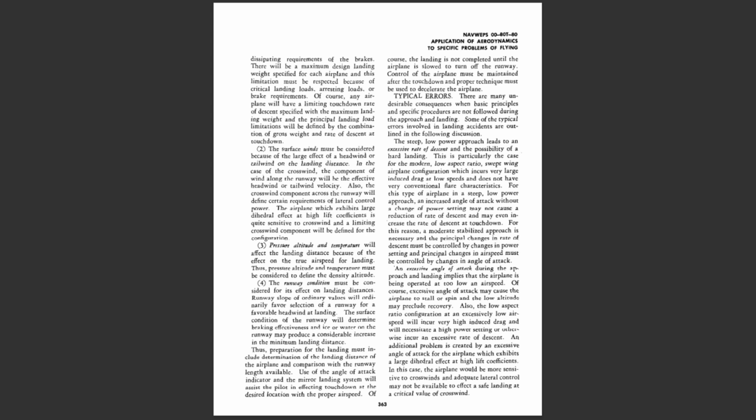3. Pressure, altitude, and temperature will affect the landing distance because of the effect on the true airspeed for landing. Thus, pressure, altitude, and temperature must be considered to define the density altitude. 4. The runway condition must be considered for its effect on landing distances.